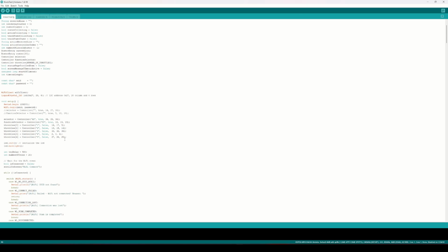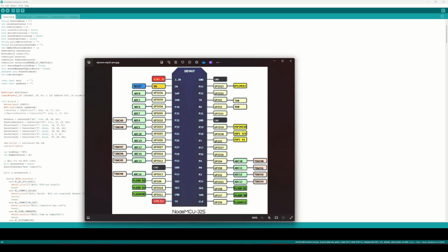And if I just grab an image, what I've tended to do is work around clusters of pins together. I would also advise using all these pins, because I don't think there's a single other pin on that board that, if you use it, doesn't interfere with something else the ESP wants to do, like boot up. So take the selector, that's 34, 39, 36. And if I drag this over here, that's just a little cluster of them there. And again, it just works through and uses all of the pins in this list here that are actually available and usable.